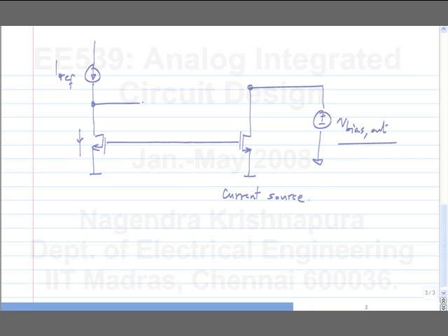So I can certainly do this, where this voltage is 0.9 volts. How do I make this op-amp? I'll make another two-stage op-amp, but this is a voltage follower. So one suggestion is to use a voltage follower. Will that work? I mean, this is also a circuit that is used.